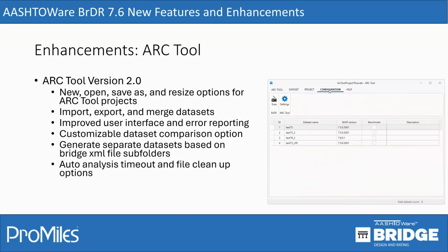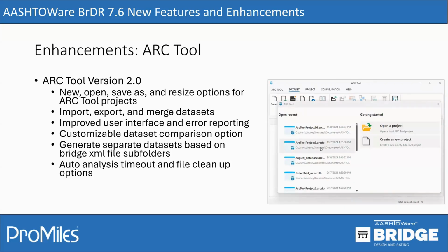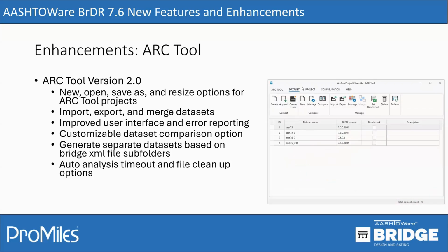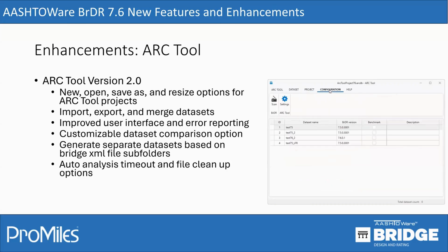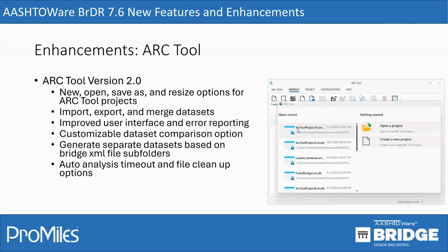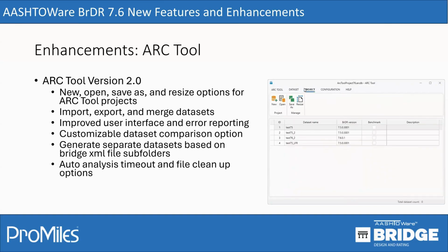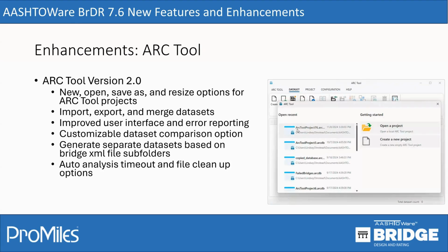And then the other nice feature is if you're running thousands of bridges, say you have 8,000 bridges in your database and you want to run all of them, it has an auto cleanup feature, which also cleans up the analysis results that get dumped into the file explorer. As you're running the analysis, it pulls the results and saves them to the data sets, but behind the scenes it also cleans up the file explorer on Windows, so that you don't run out of space as you're running those bridges.